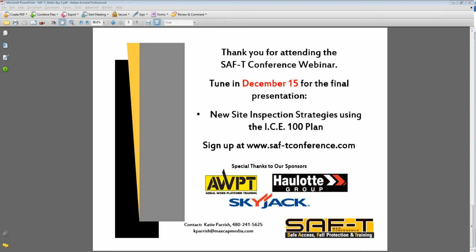Support conditions. Where would you find an engineer to find out the area that you're working your lift on? Yeah, and that one becomes a little more difficult. It really depends on what you're working on and how you're working there. If you're working in new construction and, let's say, someone's erecting a building, usually there is a site engineer who's responsible for the entire site, right? And I think at that point, you really have to approach someone there to let you know what the specifics of the ground condition are.